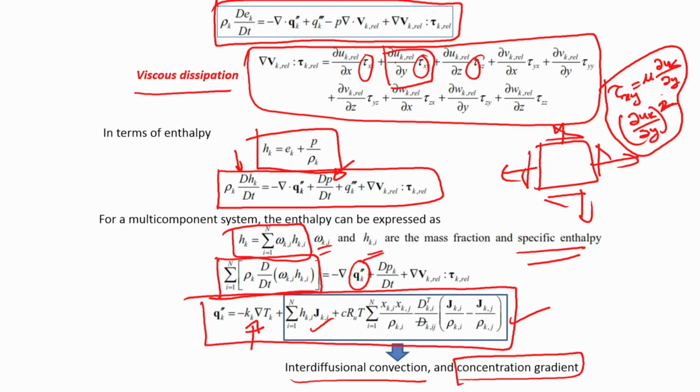As you know, concentration can be transferred by temperature gradient, similarly heat can also be transferred by concentration gradient, but these two components are strictly second order effects, and in most cases they are negligible. However, many of the equipments that we use actually work on the second order effects. One example is thermoelectrics, that is a second order effect essentially.